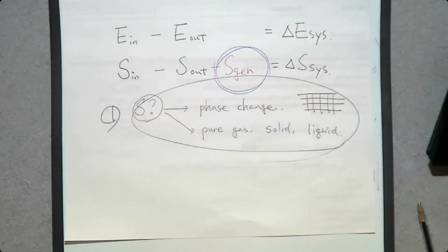And second, I told you that entropy only increases when there is an irreversibility. That means that when you design a turbine, a compressor, a heat exchanger, pump, motor, anything that uses energy, you can say when entropy remains constant, that's when the process is reversible, right? Because entropy only increases when there's an irreversibility. When the process is reversible, entropy remains constant.